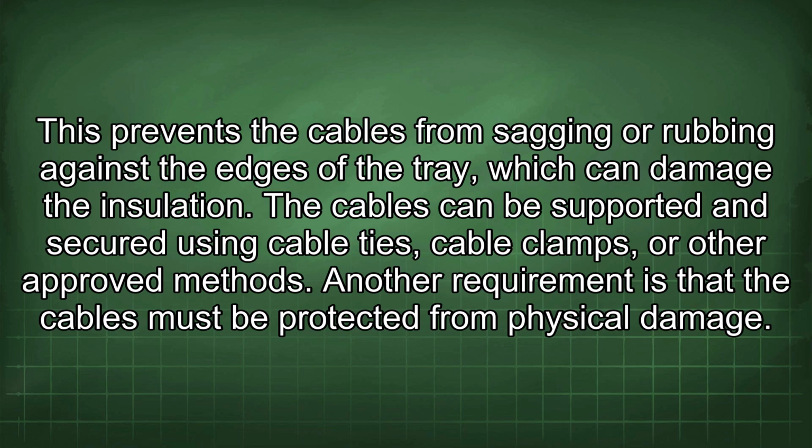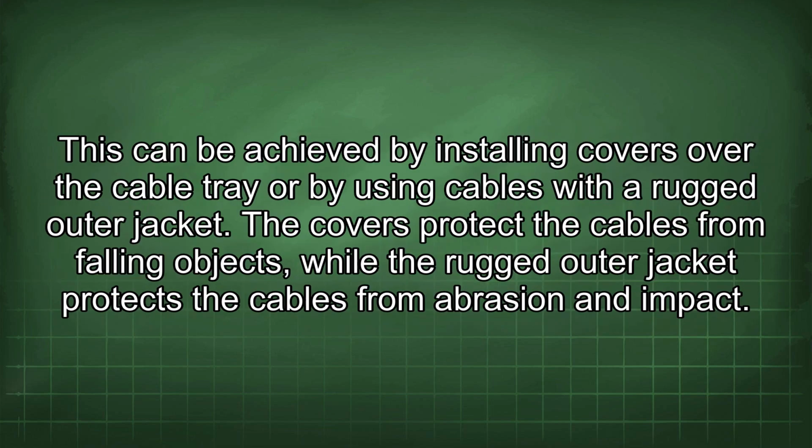Another requirement is that the cables must be protected from physical damage. This can be achieved by installing covers over the cable tray or by using cables with a rugged outer jacket. The covers protect the cables from falling objects, while the rugged outer jacket protects the cables from abrasion and impact.